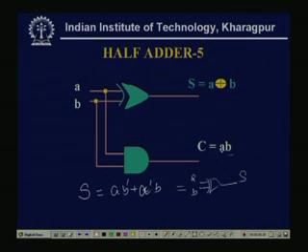Now, what is the advantage or disadvantage of that? See, first thing is, here there is no need that complemented variable should also exist, only we have taken the uncomplemented variables or the letters, and there carry is simple a b and one XOR function. So, there are 2 gates, but just notice that this XOR is not a basic gate, actually that AND OR sum AND OR realization is needed for this XOR. But now, for these MSI circuits, we can realize the circuits by XOR, XNOR or multiplexer or many other, ROMs, that is also nowadays available.